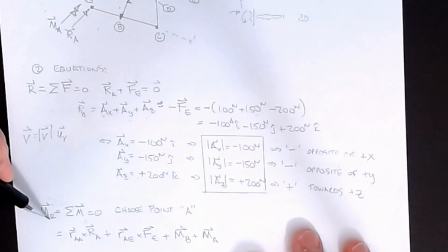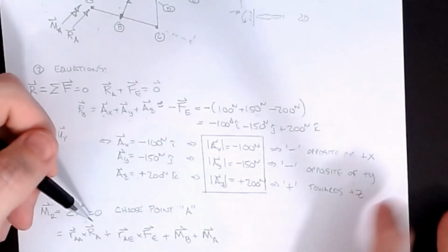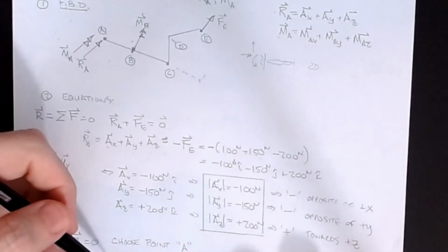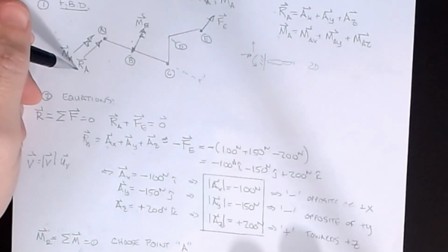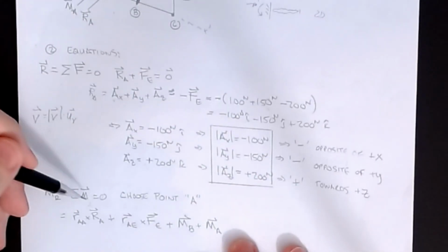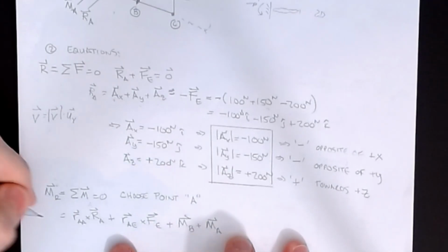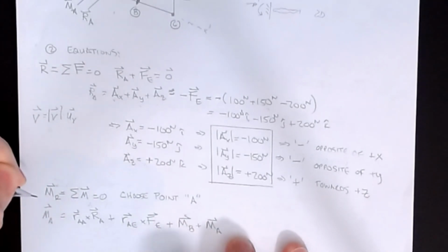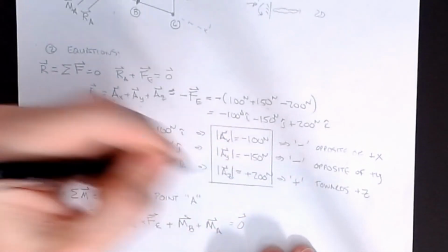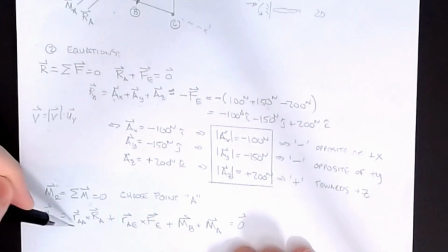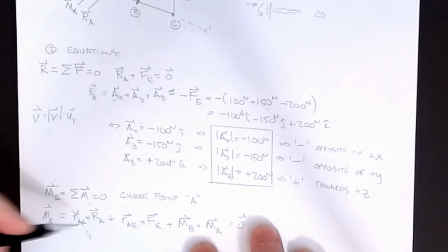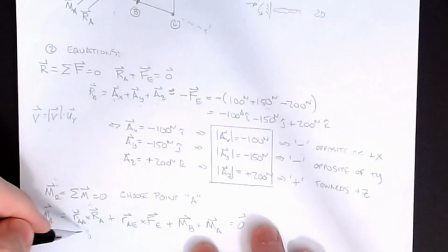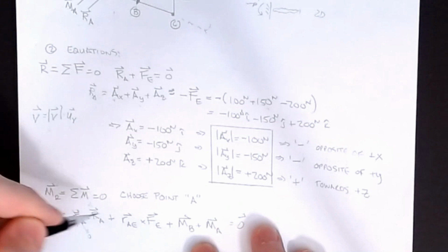Okay, so the moment resultant is the sum of the moments on the object, all equal to 0, and we're going to choose point A. And so now, again, all we're going to do is write that equation like we did in the more general example: I need all the forces, so R cross F. So my force reaction at A is at A, right? So I'm going to do a position vector from A to get me what would be a moment vector at A, and this whole thing we said has to be equal to 0. So again, force at A, moment at A, R is from A to A. Well, we know that is 0. The start and the end point are exactly the same. So this first term doesn't matter, and that's why we chose that point, to force this to be a 0 value so that it wouldn't have an impact on the calculations.